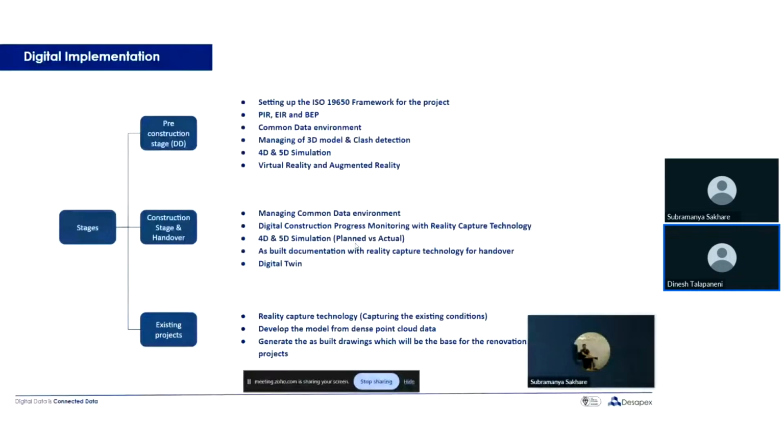So what we're doing is, in simple words, what 4D BIM is all about. You are developing a 3D model. You have a geometric 3D model with you, and we have the project schedule with us. We are trying to link the 3D model with the schedule and run the virtual construction simulation to see if our schedule is right, or if we have modeled everything, or if there are any clashes. It brings a lot of transparency and understanding in terms of communication between the stakeholders.